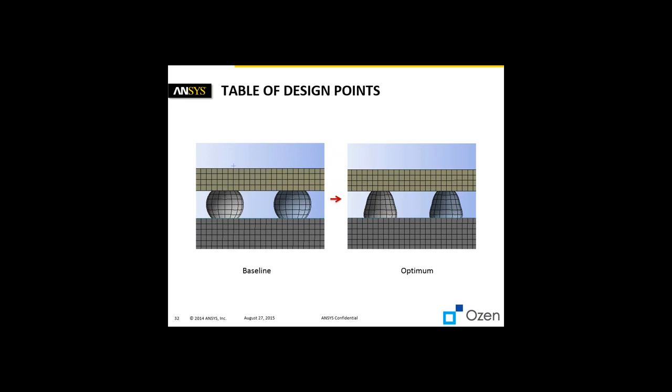Viscoplasticity, we turn on viscoplasticity, which means we also turn on time effects. Time effects are also turned on because creep is a function of time and temperature. So this was just a demo case we wanted to do really quickly. Oh, okay. But in real life, the point I guess you're asking is maybe if we had turned on creep and viscoplasticity, we may get a different shape. Right. Yeah, that's a good point. This is just for static. This is what we got.